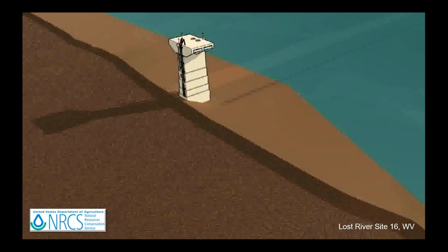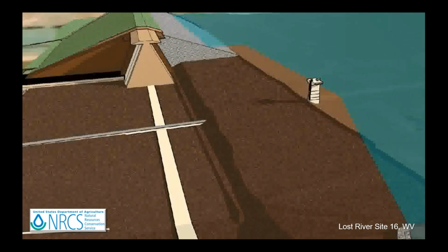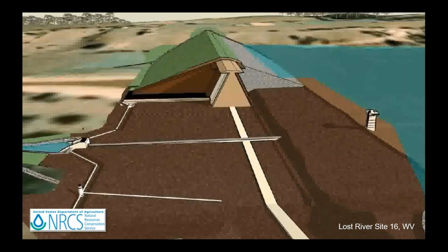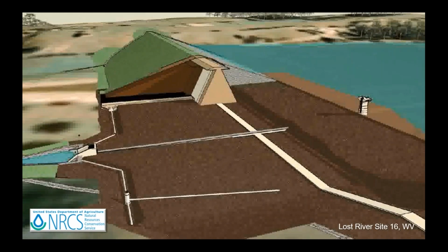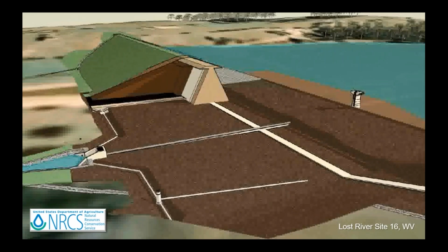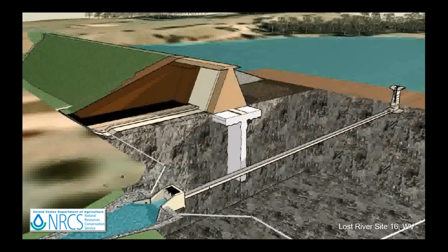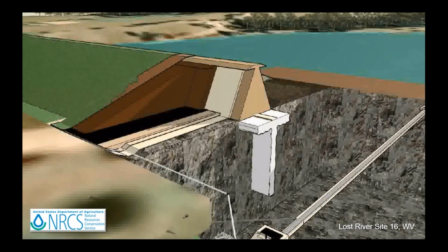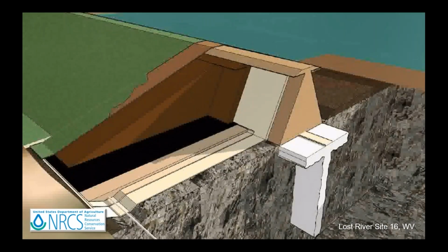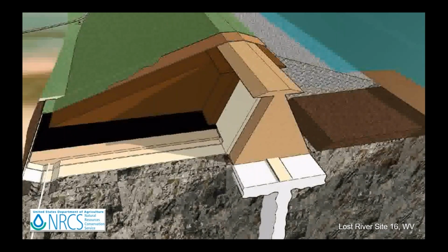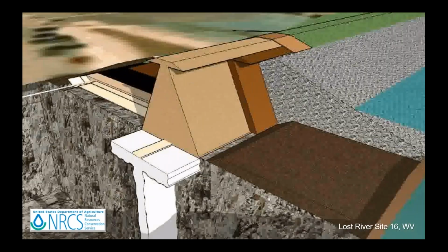And now we're cutting away from the dam and we're taking a cross section. And you can see how the embankment is zoned. You have the clay core, a concrete plinth, the very important chimney drain and blanket drain to control any seepage through the embankment. And then you can see the conduit, that's the drain conduit that's used to collect the seepage and discharge it through the walls of the impact basin. And this particular one has a grouted foundation as well as consolidation grouting at the contact between the clay core and the bedrock. So a very well-designed modern embankment dam.